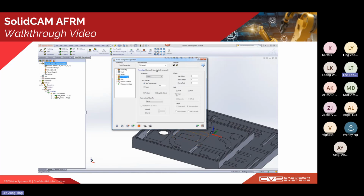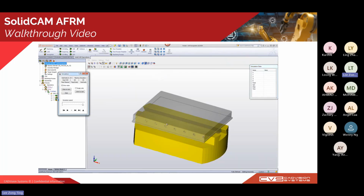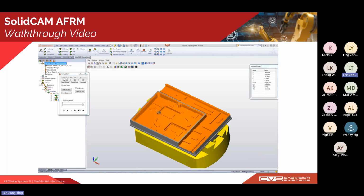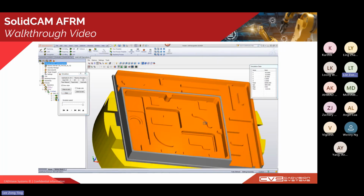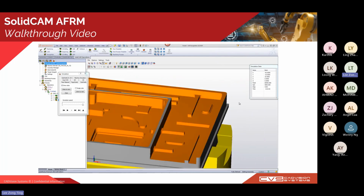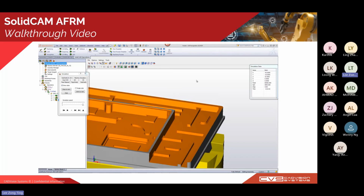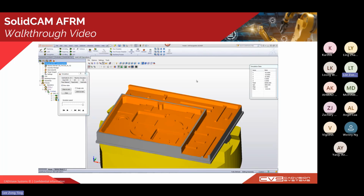And you can see here we can specify the technology we want to use for an open pocket. And after we are satisfied with those parameters we entered, we can go ahead and save and calculate and simulate it to see if the result is what we wanted. So you can see during these simulations, the pocket has been successfully milled in one single operation. Typically we will need multiple operations to do this, but using the AFRM module, we only need to specify one operation and it will pocket the whole body for us. So this greatly saves your programming time.